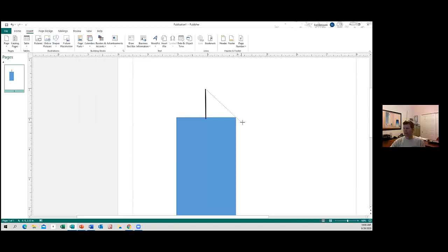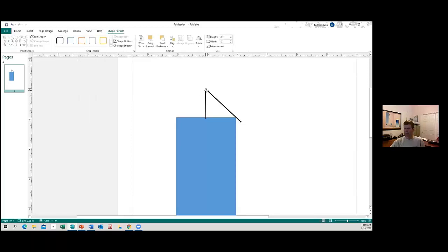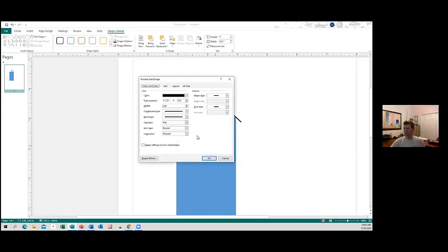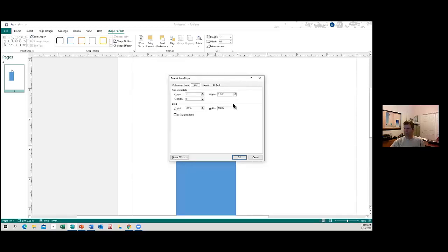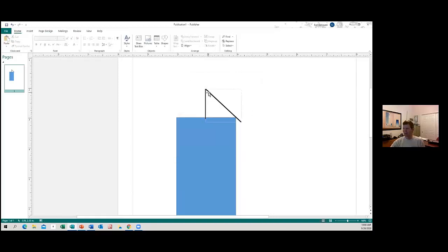Earl? Yeah. Earl, just a suggestion. If you go back to your vertical line, click on it again and go to the size for it. Go back to your format. If you go to size, you've got to click on size. So you see, if you look where it says width, make the width 0, and then the line will be vertical. Oh, okay. I learned something new. Cool. Okay, thank you. No, it's good for everybody.